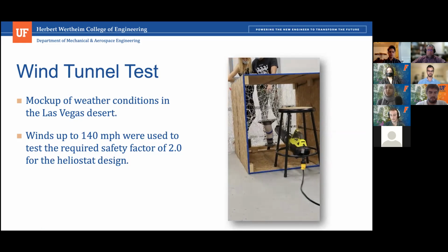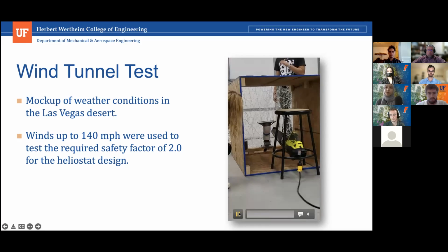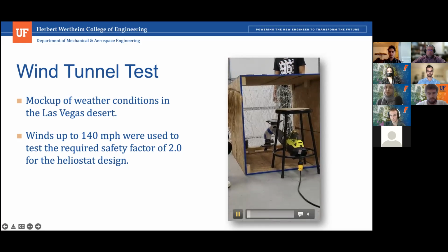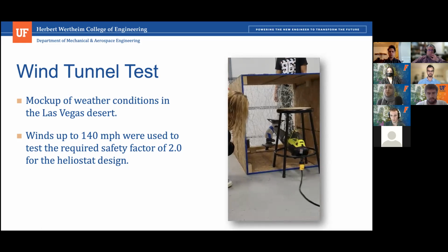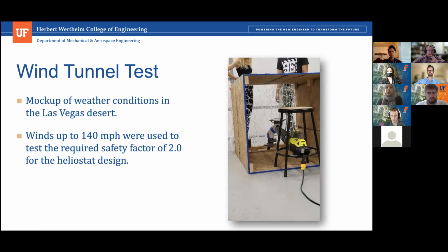So that means it was mid-development in terms of programming, but structurally it was aerodynamically representative of our final model. So we physically locked down the heliostat using a quick release plate on the bottom of the base, and we put it through a series of tests in different mirror configurations at different wind speeds. So we performed tests at basically 2 mirror configurations.